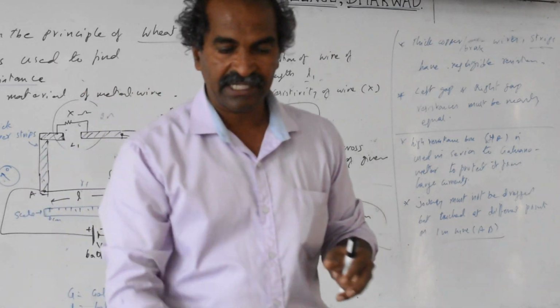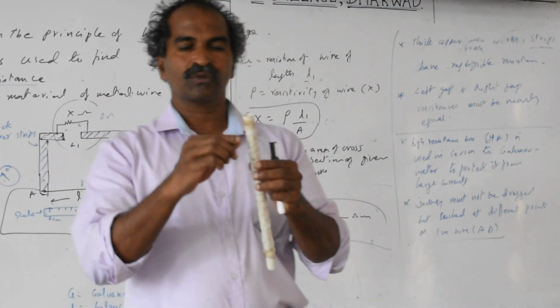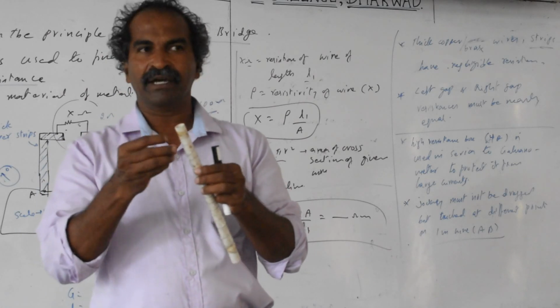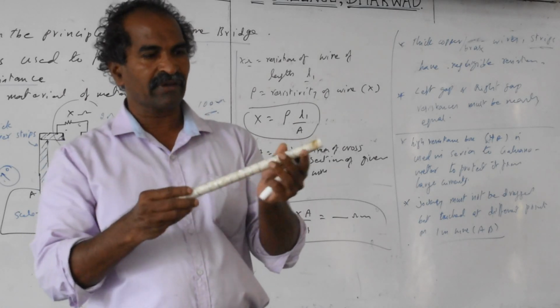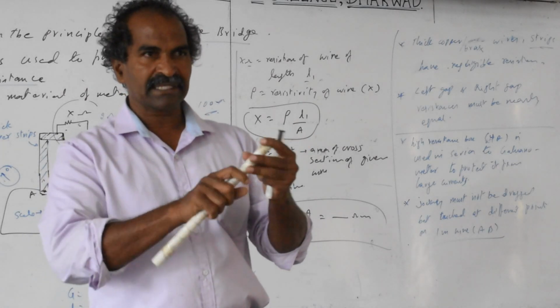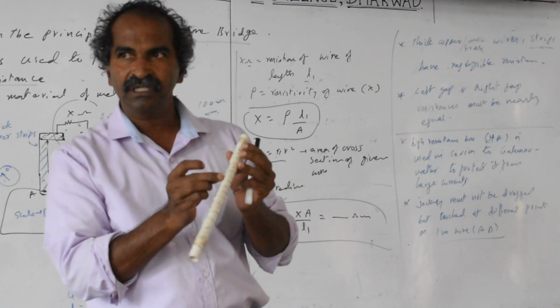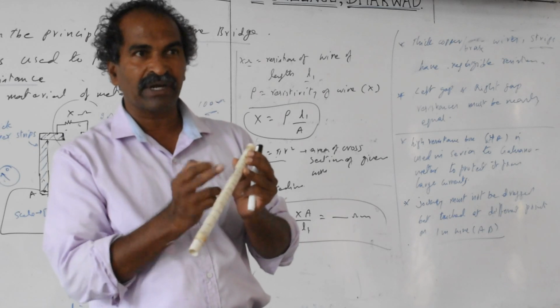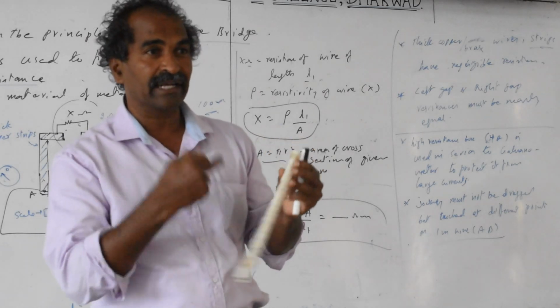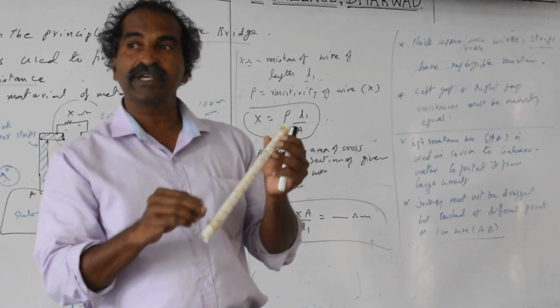But this wire does not have the plastic covering. Here, you are given a plastic pipe with insulation tape kept on it so that the turns don't touch each other. If they touch, current passes directly from one turn to another, not along the length of the wire. Current should pass through the length of the wire, then only can you consider its total length.